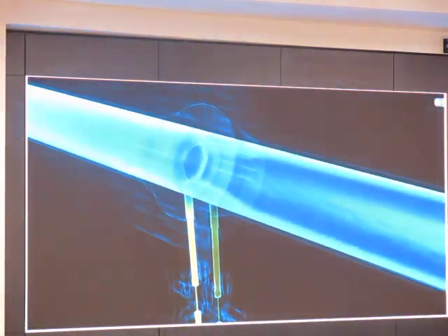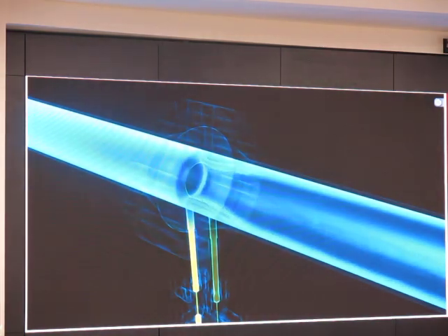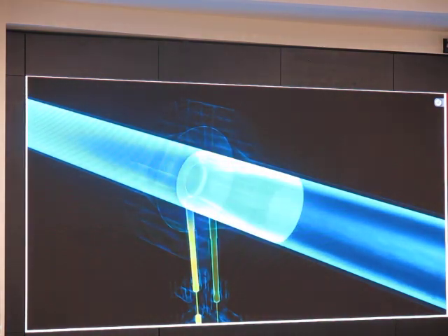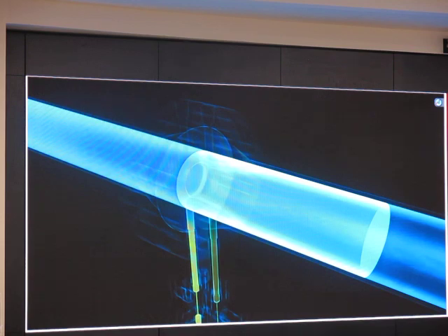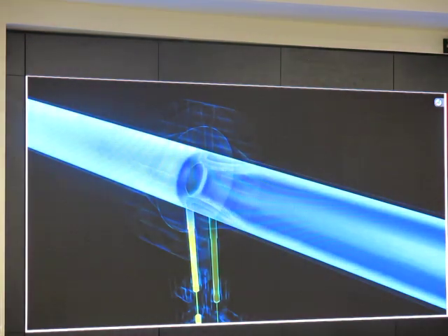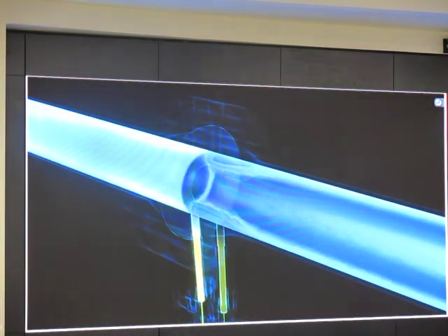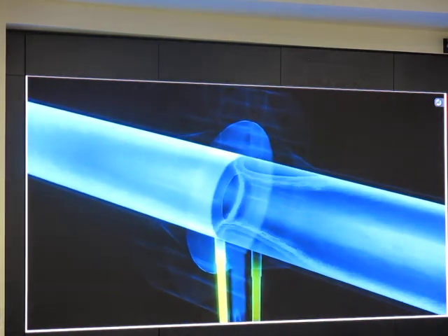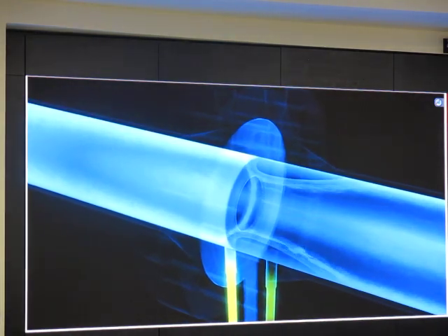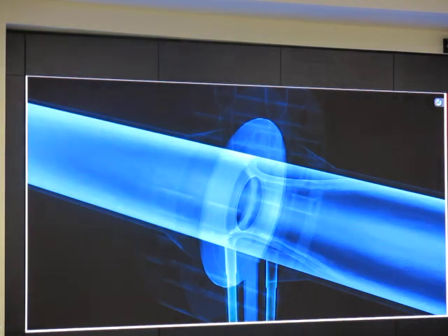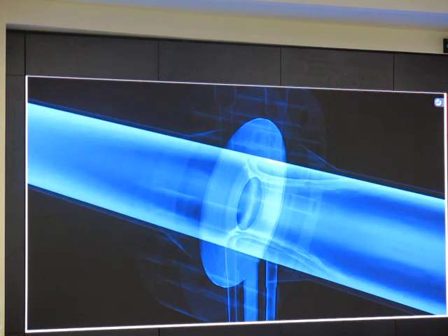This pressure difference is a direct measure for the flow velocity, and thus the mass and volume flow in the pipe. The higher the flow velocity and the resulting drop in pressure around the orifice plate, the greater the differential pressure measured. In numerous industrial applications, the orifice plate covers many needs of flow measurement technology.